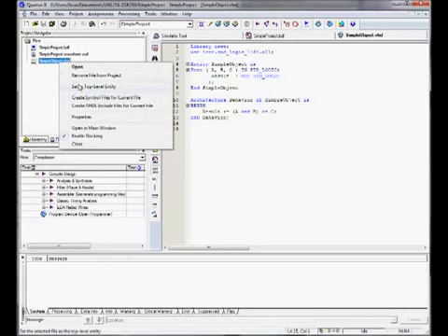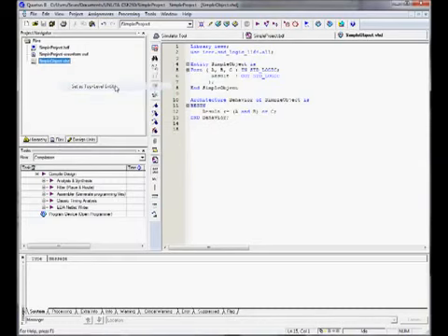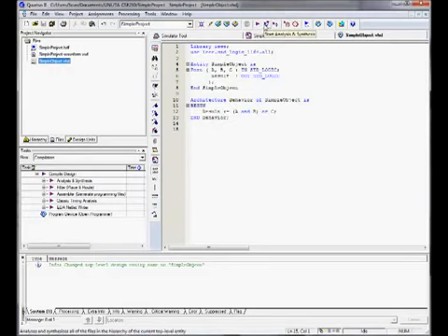Anytime you hit compile over here, it only compiles what it considers the top level entity and anything that's necessary to make that top level entity. So if your project does not include our simple object, it won't do anything. So for our purposes, we want to make it the top level entity, and then we're going to hit start analysis and synthesis. Once again, it'll compile.